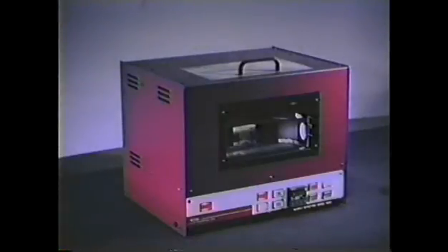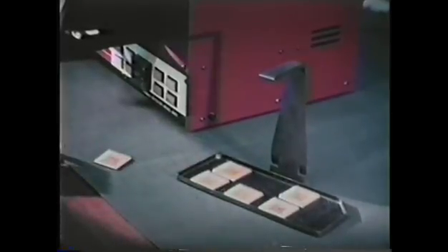This is because with the bubble test, false leaks cannot be visually discriminated from true leaks, so they're rejected along with the true leakers. Like overkill, escapement is a costly result of user subjectivity. Escapement can occur if the operator doesn't pay full attention during the entire 30 to 60-second test. A device can emit either a short burst or a fine stream of bubbles, which could be easily overlooked, thus allowing a non-hermetic device to pass. Also, escapement can occur when the operator pulls the wrong device from the parts tray.